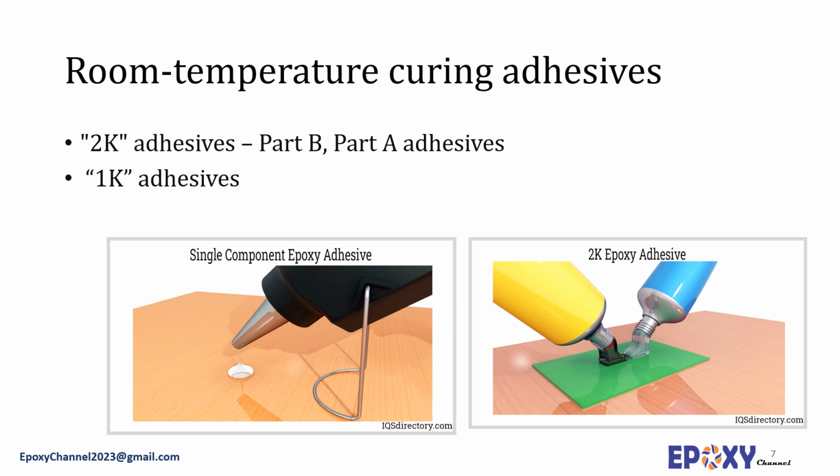One component room temperature cure epoxy adhesives, also called 1K adhesives, are also available, and for their curing, an energy source such as UV light or EB is required. Compared to 2K systems, one component epoxy often has a shorter shelf life, for example 3 to 6 months, whereas each part in a 2K component room temperature epoxy adhesive often has a shelf life of up to 6 or 12 months. Compared to 1K room temperature curing adhesives, the 2K systems of the same type exhibit greater flexibility, resulting in better low temperature performance, higher degree of peel and cleavage strength, and generally higher bond strength to flexible substrates.